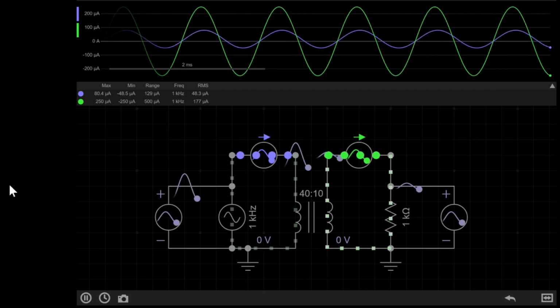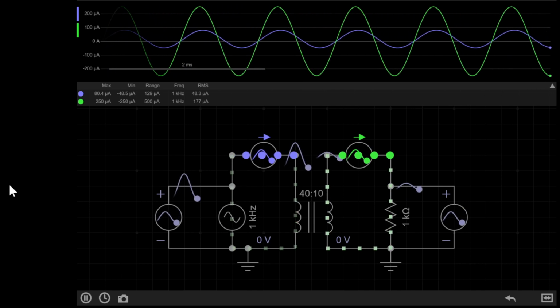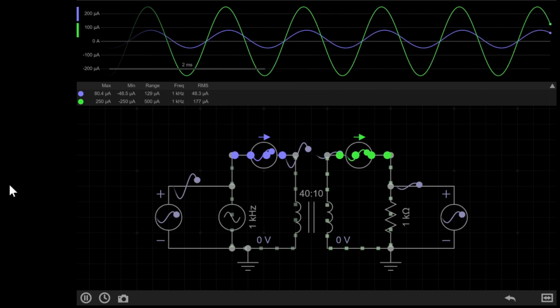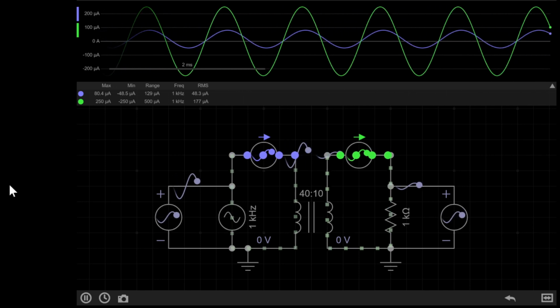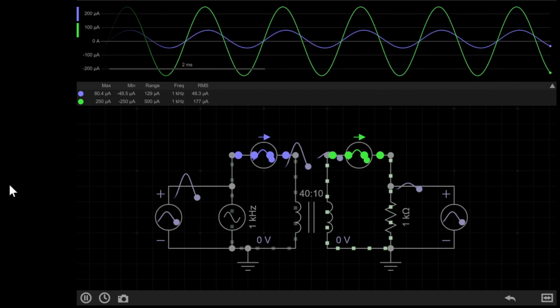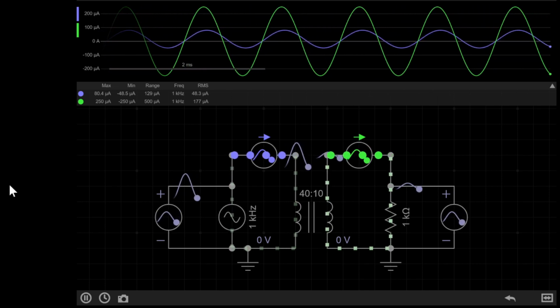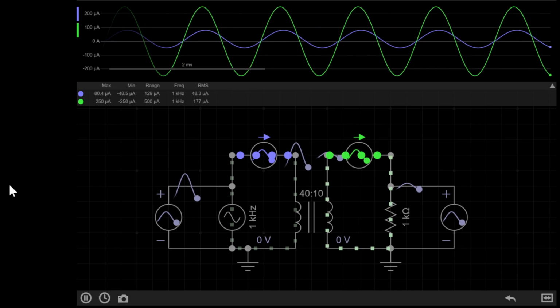One other big benefit and use of transformers is to give what's known as mains isolation. If you have a transformer, even a 1-to-1 transformer transforming a mains voltage, it becomes much safer. This is because if you touch a main signal wire that's not isolated, then current can flow through your body to the ground, electrocuting you.